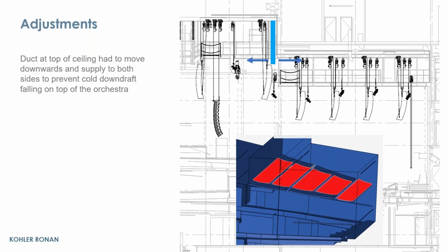So we actually took a look at natural ventilation hours in New York City. There are a couple of ways we do it. If the outside air conditions are perfect, we run the unit in full economizer mode, which means you're bringing in 100% outside air, bypassing the cooling coil, and just using the fans to provide air directly. But because you're working with material finishes, you also want to control your humidity, which is really critical as well.